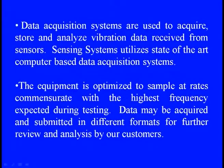Data acquisition systems, generally called DAQ systems, are used to acquire, store and analyze the vibration data received from the sensor, and the sensing system utilizes a state of the art computer based data acquisition system. The equipment is supposed to be optimized to sample at rates commensurate with the highest frequency expected during the testing.